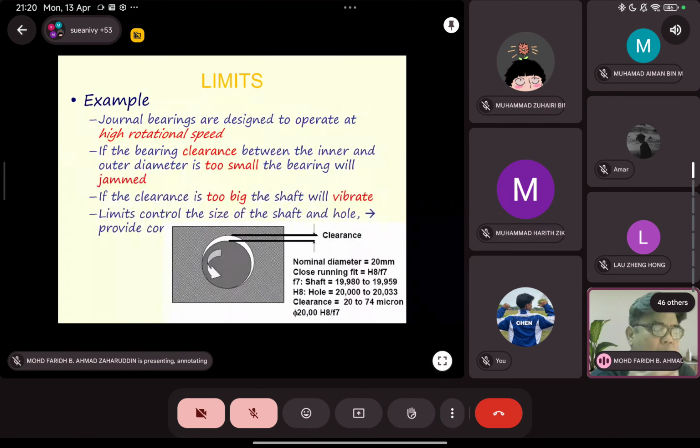If you want a good engine oil, it will be very expensive. If you buy a cheaper oil, for sure you can use it, but you need to change it often. With fully synthetic oil, you use 8,000 to 10,000 kilometers for a car, but with normal oil, maybe 3,000 to 4,000 you have to change. As long as you change frequently, it will be okay. That is the theory, simple as that. Same goes with a motorcycle. You have to check your engine oil, its viscosity. Don't wait until it's dark before changing, because sometimes there is no pickup and the engine will have high vibration.